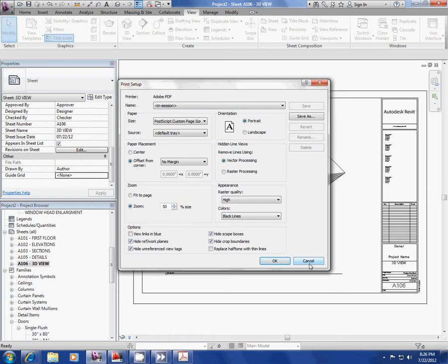Or you could set up your sheets initially 11 by 17. That's another way of doing it as well, is importing a title block that's 11 by 17 if you have a standard 11 by 17, so like an RFI template or an ASI template or something like that. You can load those things in and print them at 100% and they'd be 11 by 17. Because then you would just build it, and then if something was bigger, you just adjust the scale of every particular little viewport, essentially.